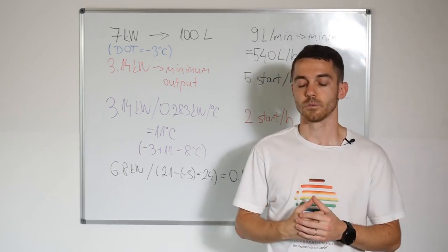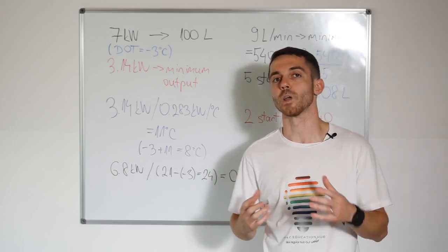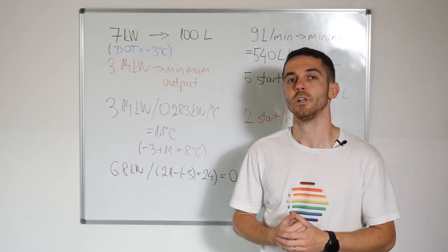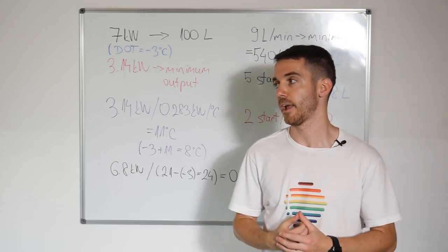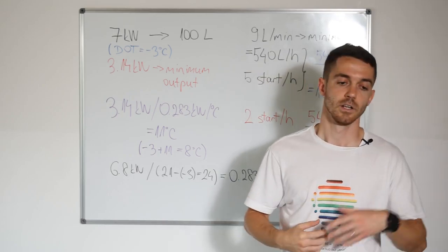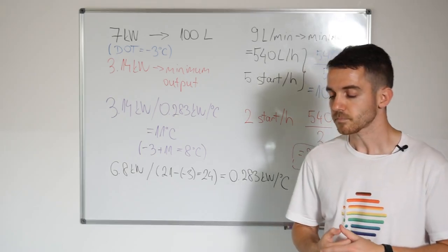One of my colleagues said that in some countries it's mandatory to have individual regulation. With individual regulation, you are reducing the volume of the installation, and you will have a lot of cycling. Lots of cycling means lower COP, more consumption, and so on.